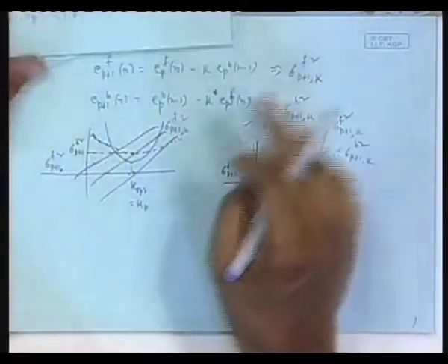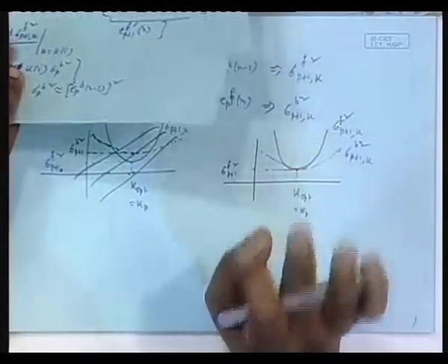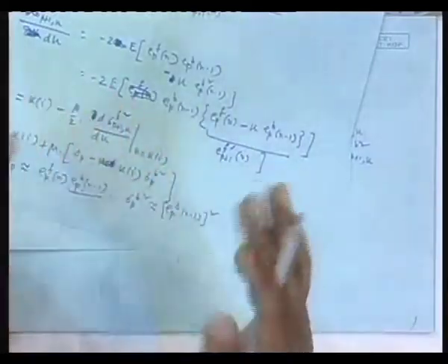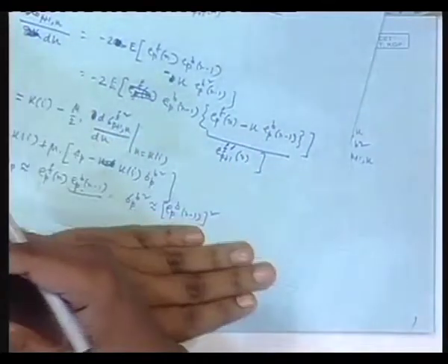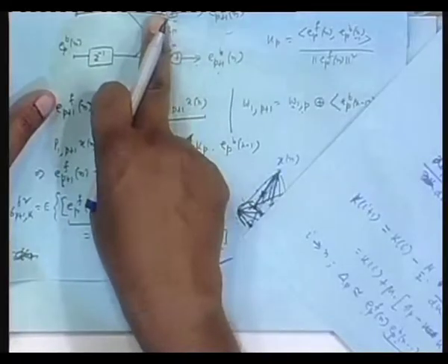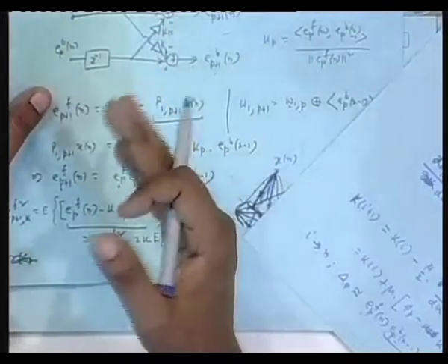But in the lattice, I want them to be the same, isn't it? Because I know from theory that both the arms should have the same coefficient. That is not guaranteed in that separate business of LMS updating either the multiplier of this branch or the multiplier of this branch. How do we get rid of that problem?